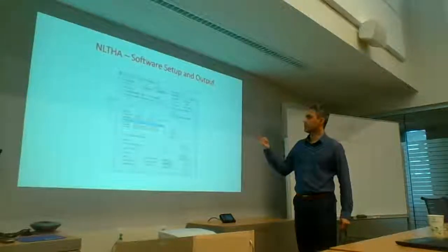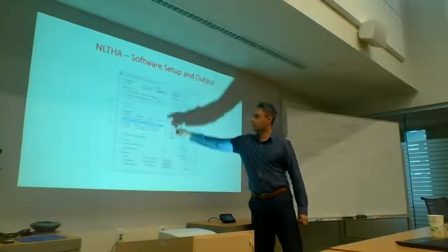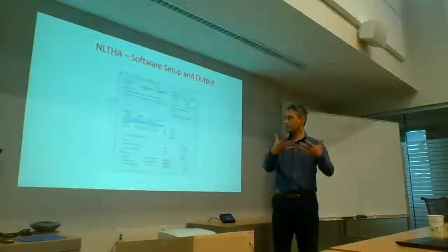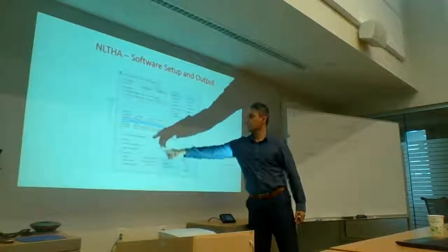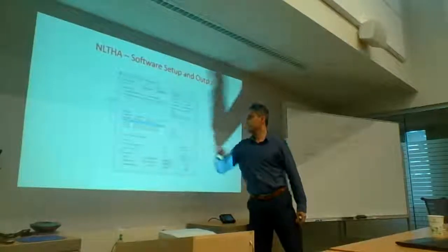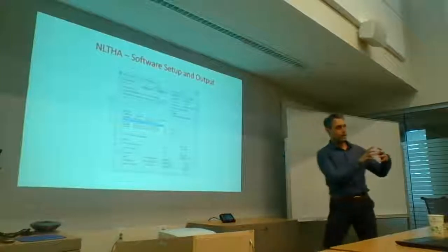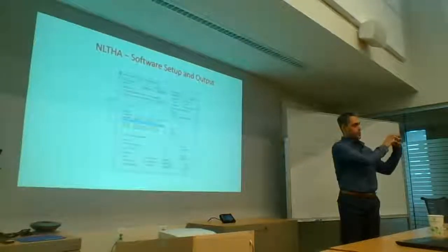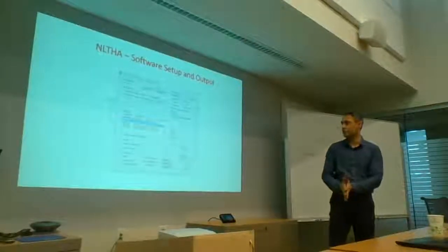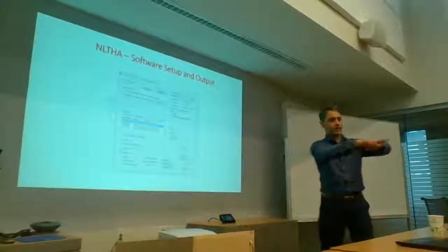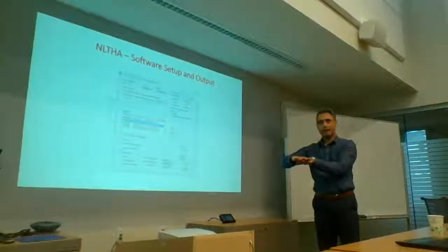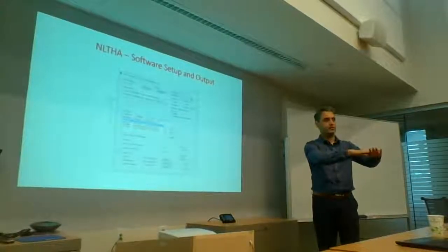So this is like a load case that's going to start from the dead load case. It's going to take the hull abutment X and Y, which is tied to the pile time histories, and then it's going to tie that, the caissons are tied to the rock. Okay, so now you're applying the time history for soil to the pile location and for rock to the caisson location. So within this, you've got X and Y applied at the abutment, and you've got X and Y applied at the caissons, but they're different time histories.